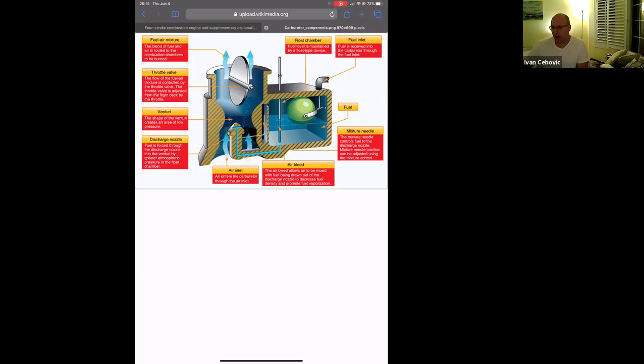Okay, that's a good one. We definitely want to know what's going on with the fuel. Can I ask you another question? You said that fuel tanks were interconnected. Why is that? Why wouldn't we just have one fuel tank and then another? Why do we need to connect them, to cross feed them or something else? No, it's a cross feed. The idea is that you don't want an imbalance, one wing drawing more gas than the other, and ultimately having an imbalance in terms of weight.